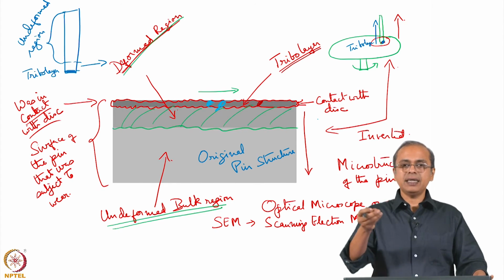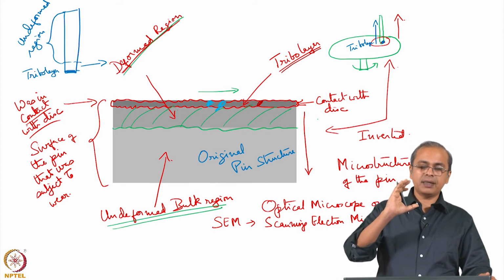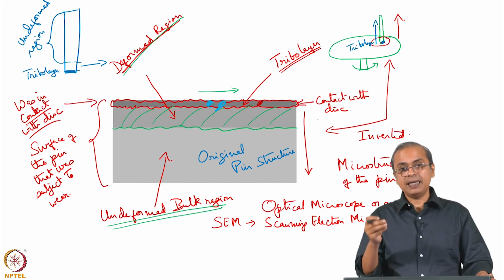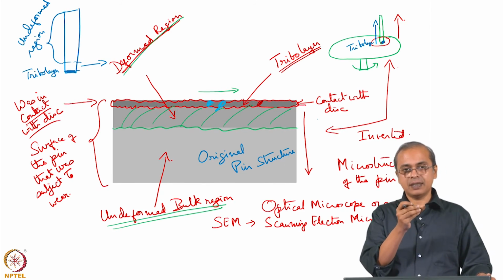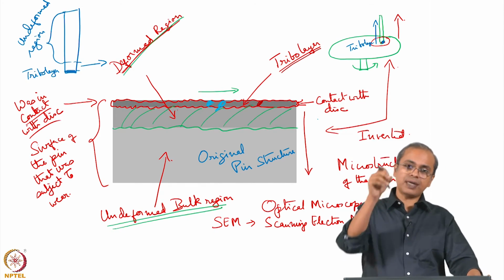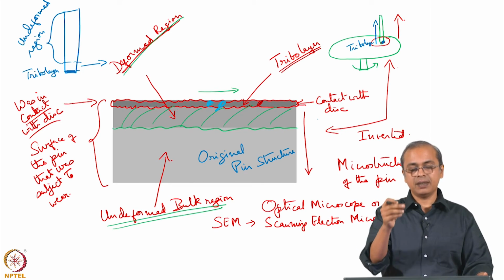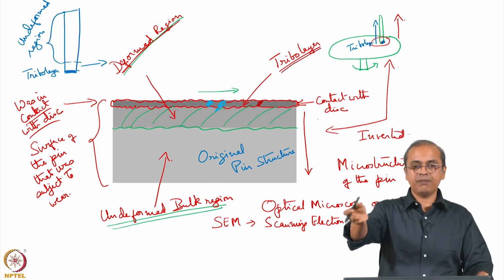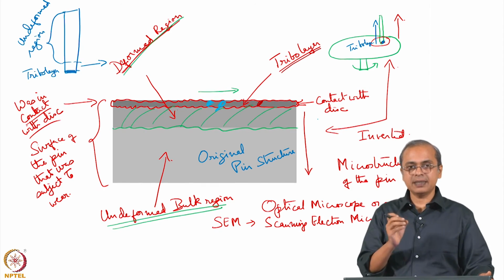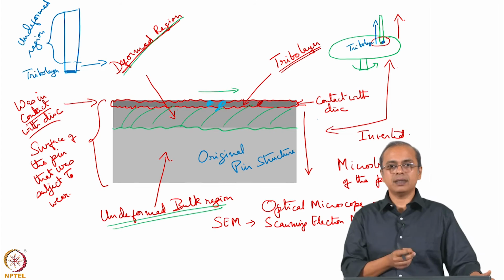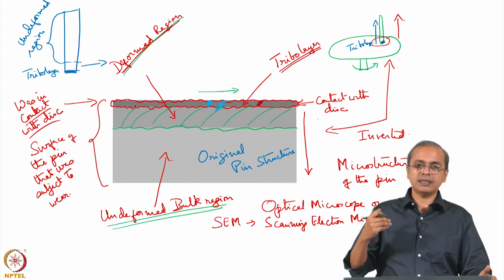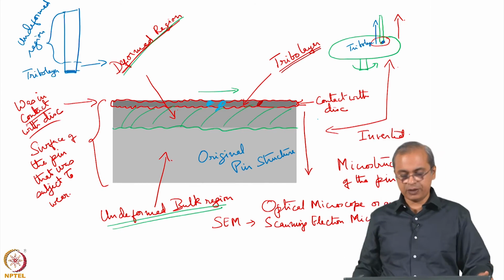It is like you have this muddy water, as I said, that is flowing through a pipe, and let us say it breaks off some particles of the oxide layer of that stainless steel. Then those particles further impact the pipe further down the line, and so both the mud particles in the water as well as the debris that has come from an earlier location in the pipe, both of them act on the later location of the pipe.